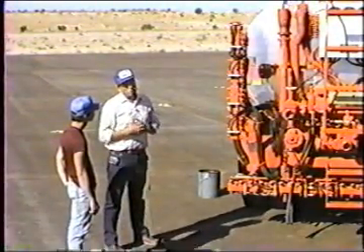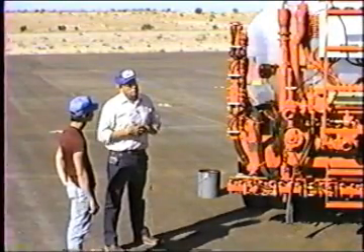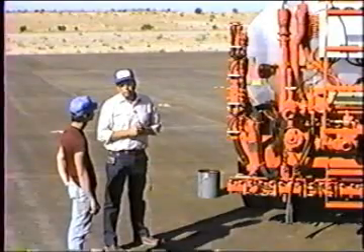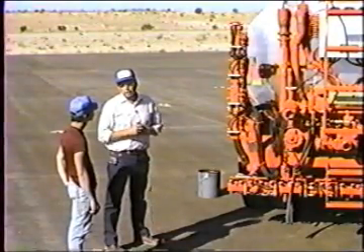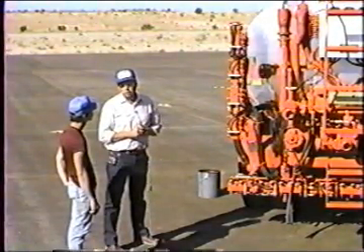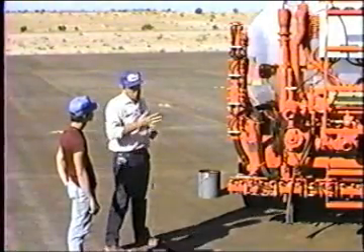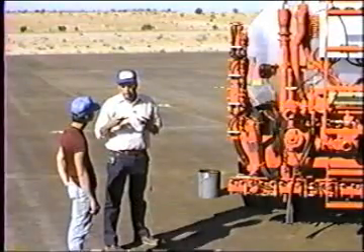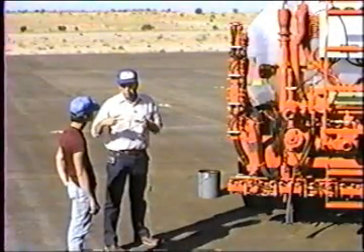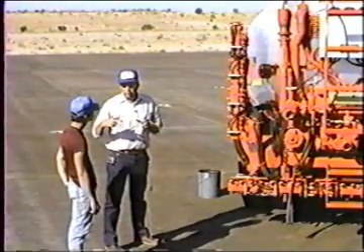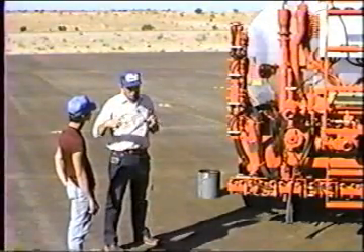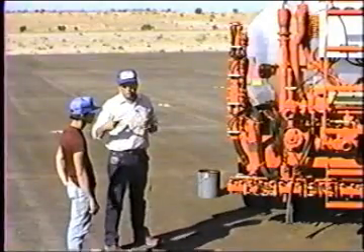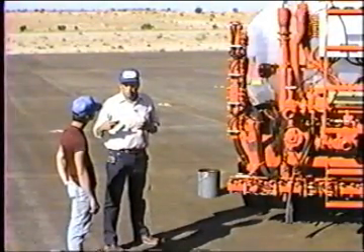Well, when you started the job, the engineer told you the specific rate that he wanted. He might have said, I want 0.40 gallons per square yard, 4/10 of a gallon to the yard. Okay, when you spray across those pads, then they'll pick those pads up very carefully, individually, and weigh each of those pads on a precision scale. That's what's in the yellow van. They'll precisely weigh each of those pads and compare their weights and calculate the rate that you put on there.